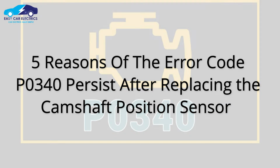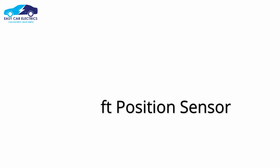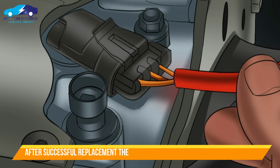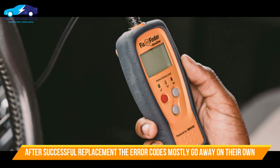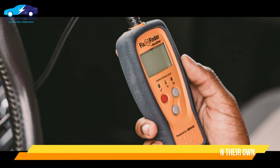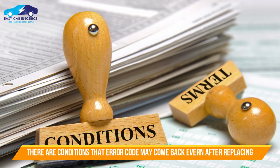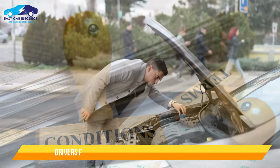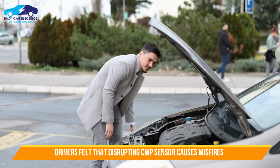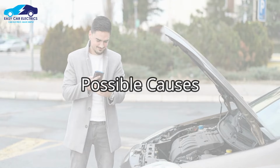5 reasons the error code P0340 persists after replacing the camshaft position sensor. Once you have replaced your old faulty camshaft position sensor, the error codes shown on the OBD screen will most probably go away when you erase the fault codes and rerun the diagnostic test. There are certain conditions in which the fault codes on your OBD2 scanner persist even after replacing the camshaft sensor with a new one. Many drivers felt that disrupting the signal from the camshaft position sensor can cause misfires and suboptimal fuel-to-air mixtures. Here are the possible causes behind the fault codes on the screen.